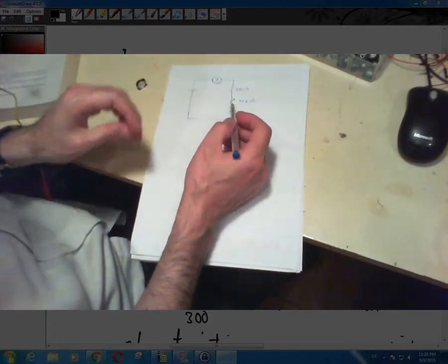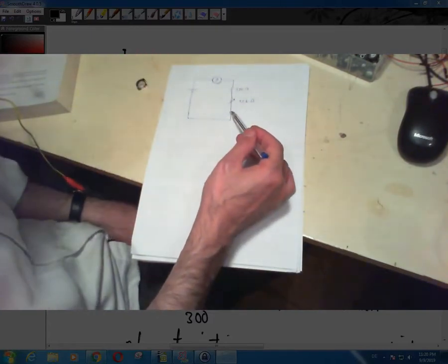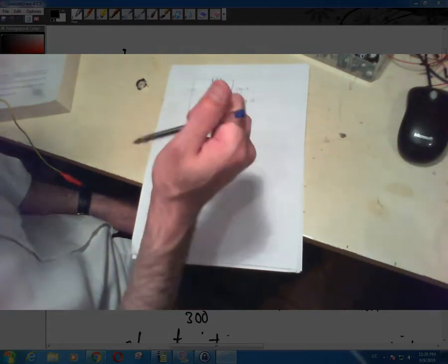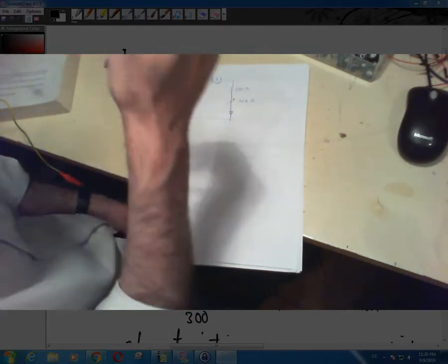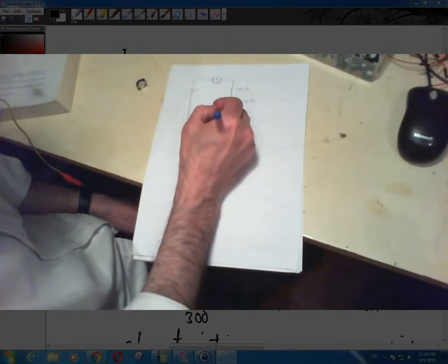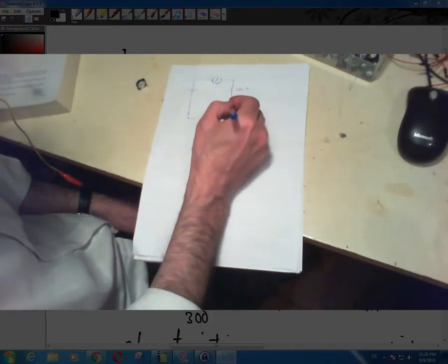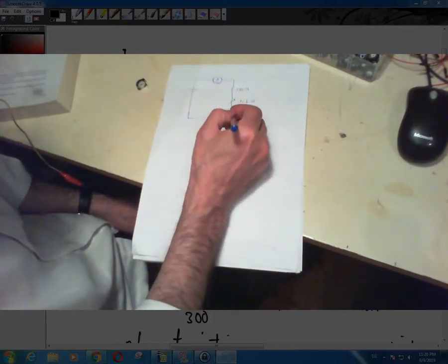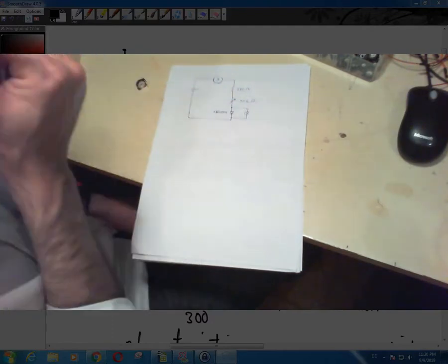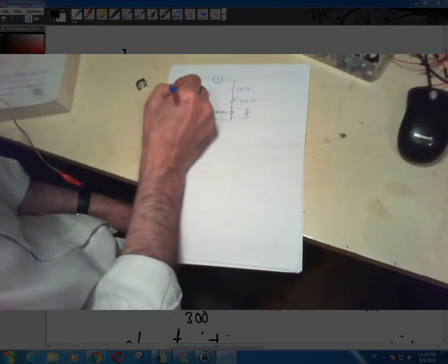And the diode is forward biased, meaning that the anode is connected to positive, the cathode is connected to negative. Okay. Now this is for example, 1N4004 that I'm using, and I will use a voltmeter over here in order to watch the voltage on this diode. And this is a 9-volt power supply.